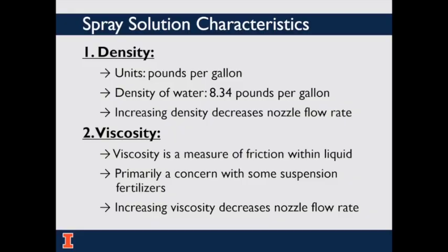Up to this point, we haven't discussed the impact of the physical properties of a spray solution. Calibration and flow rate information for water is listed in nozzle catalogs, but when switching the carrier from water to a fertilizer, adjustments must be made to compensate for the different spray solution properties. One property is the density, or weight per unit volume.